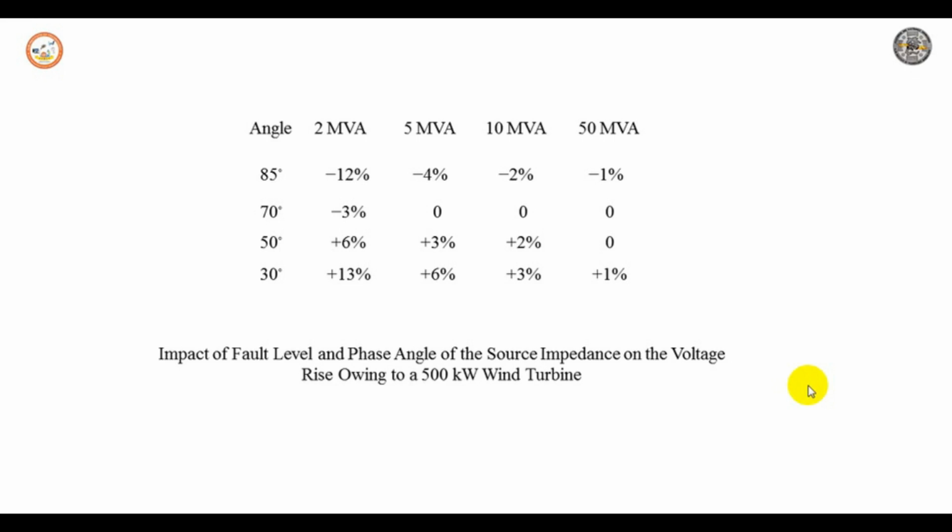The maximum voltage magnitude rises from 250 to 254 volt, within the 110% over voltage limit. This would be an unacceptable over voltage, although it occurs only for a small number of days per year, and only for a few customers.